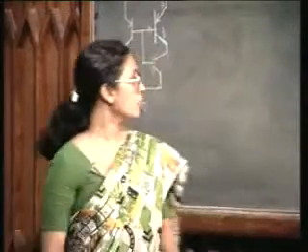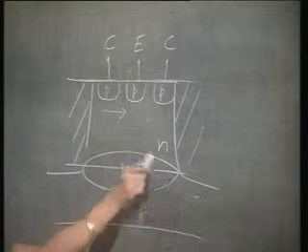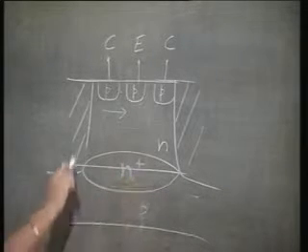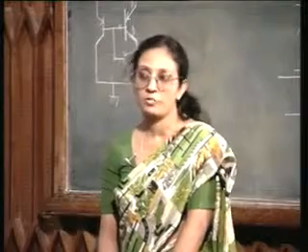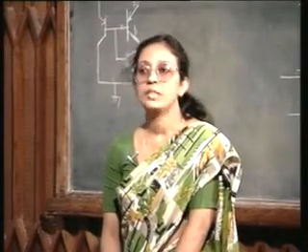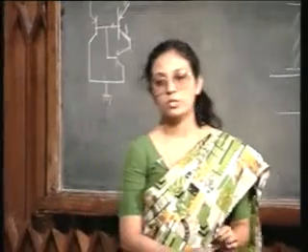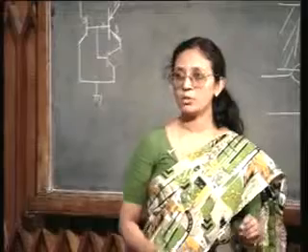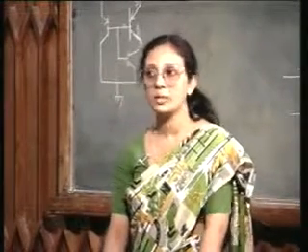However, if you look at this parasitic PNP transistor, its gain is very low because of the N plus buried layer. Because of the presence of the N plus buried layer, which is the base of this PNP transistor, the gain of these parasitic transistors is going to be very small, and therefore, it is not going to affect your actual PNP transistor performance to a large extent.